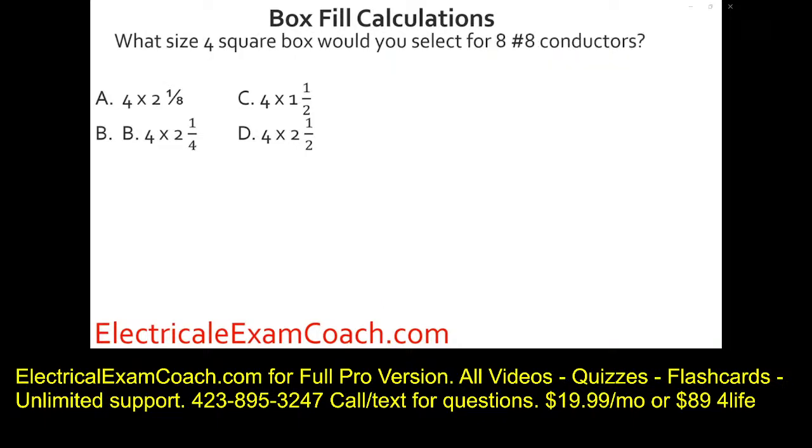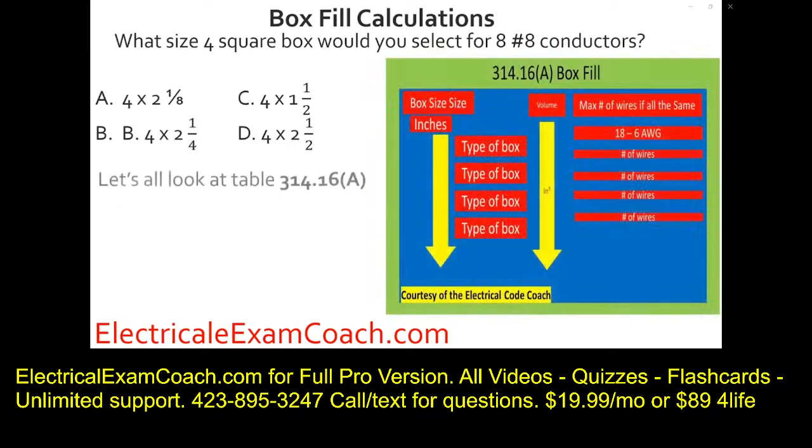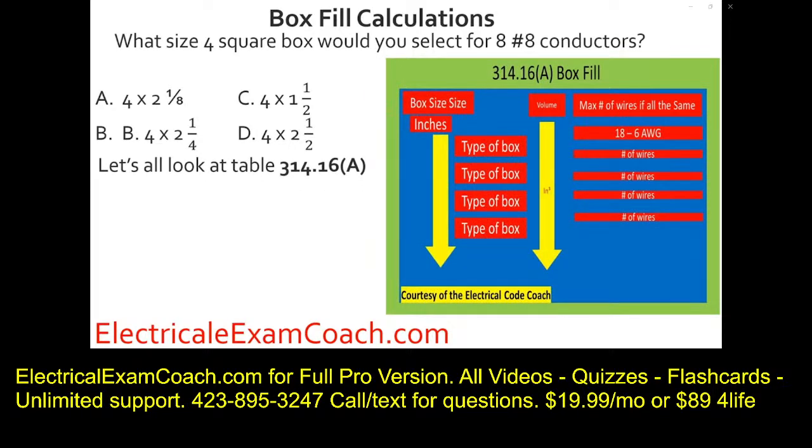What size 4-square box would you select for 8 number 8 conductors? We head to 314.16(A). We're going to start here on the right-hand side and we're going to find our size wire. Then we come down and make sure that we're in the right type of box. We cross over and we're going to find that it's A.